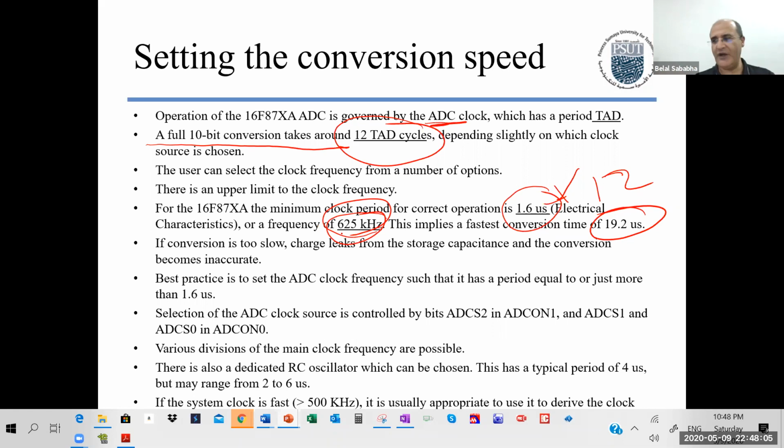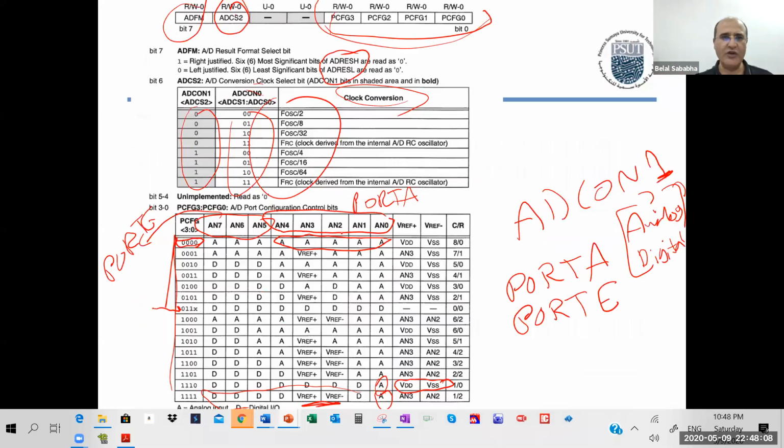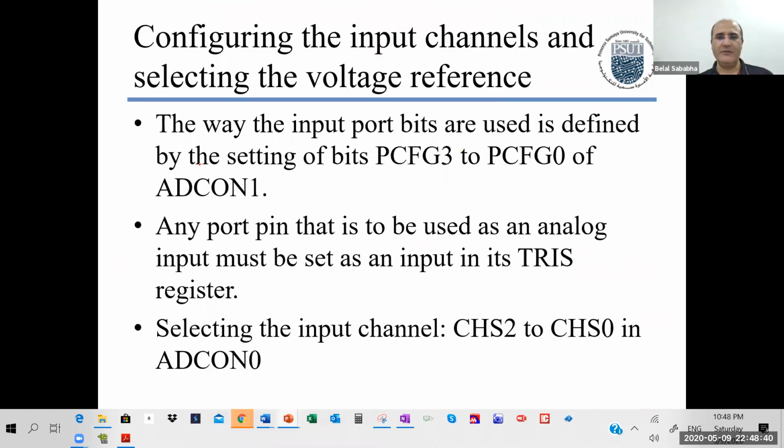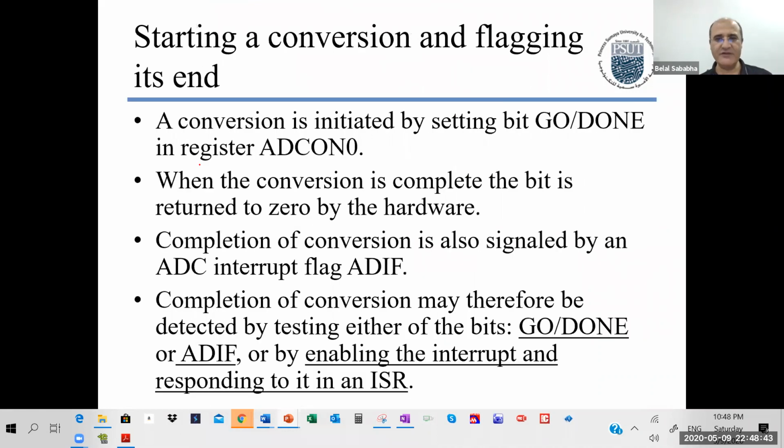Because our oscillator clock is 8 meg, if we write our program to divide the 8 meg oscillator clock by 16, we'll get 500 kilohertz. Right? Our oscillator clock equals 8 megahertz, divided by 16 equals half a megahertz, 500 kilohertz. Yes. Okay. So these are the bits we want to set like this. Okay? And then arranging the registers, everything is all good.